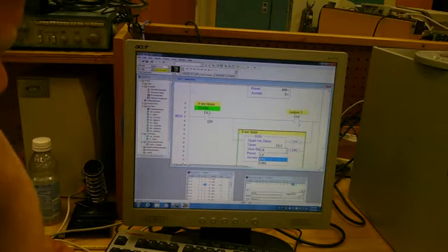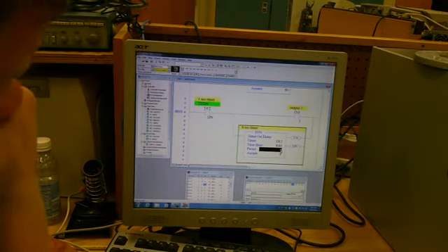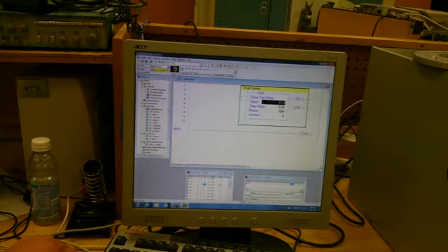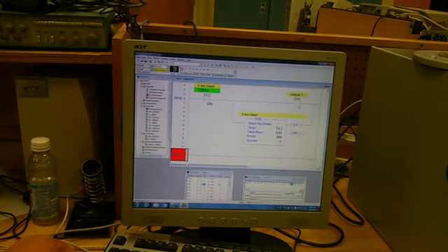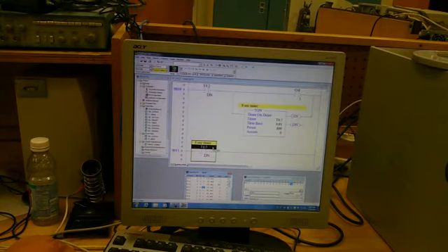Okay, so we'll do the same thing. It's more fun having hundredths of a second show up than having whole seconds show up because it just takes too long for a whole second to show up. And then we need one more rung. And we need a T3 done bit. T3 done, and then an 8 is going to show up.